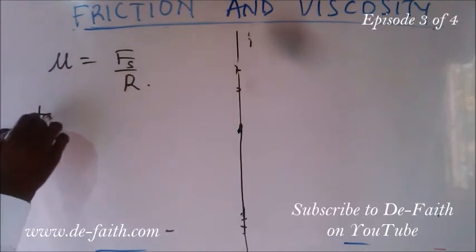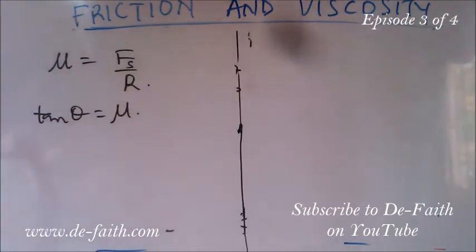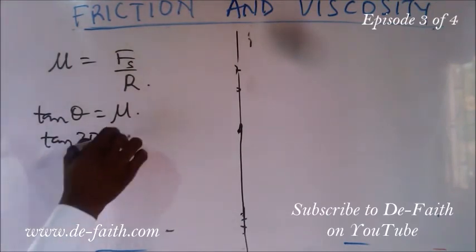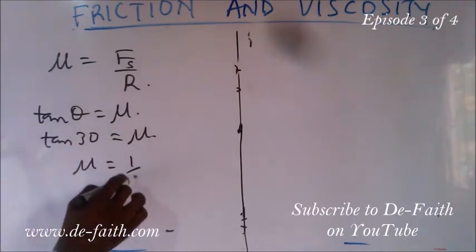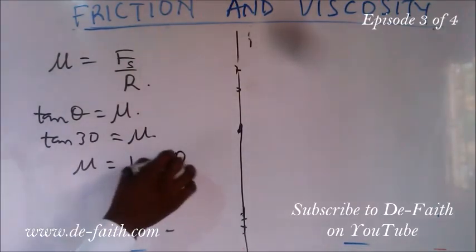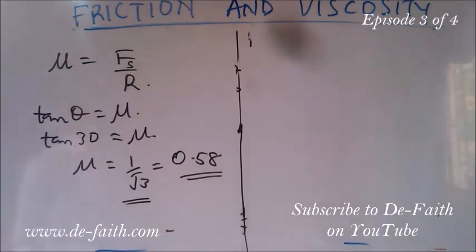But we also know that tan theta equal to what? The coefficient of static friction. And so theta is what we're given, tan 30 degrees equal to this. So just go straight forward and find tan 30, which is 1 over root 3. And in decimal becomes 0.58. So this is the coefficient of static friction.